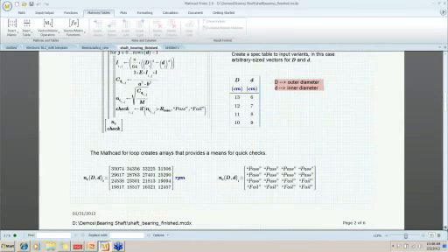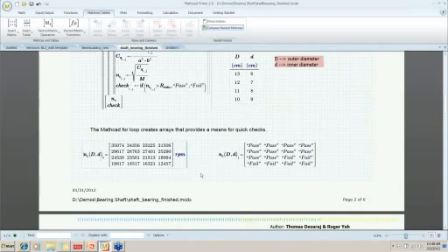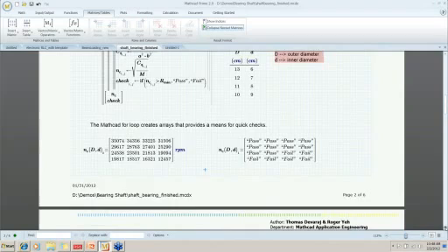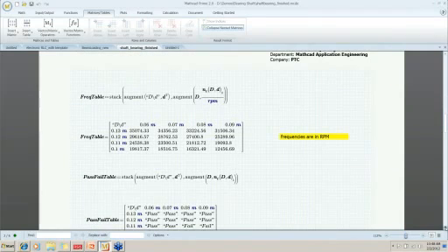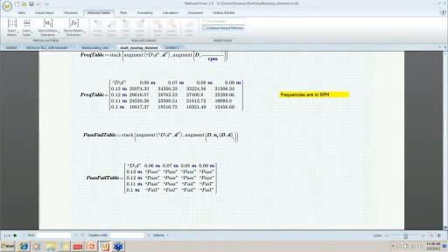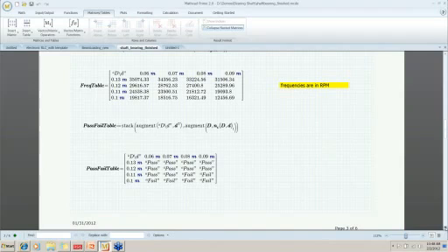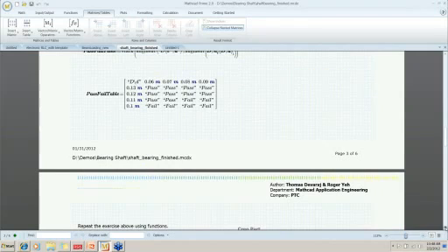And so here's our table of outputs. These are all of the critical shaft speeds we calculated, units of RPMs. Here's the pass-fail table. We have 16 entries. And all we're doing here is putting some column headers and row labels on so that we know exactly what numbers the calculations are using for outer and inner diameter. That's all that's doing. And then down here we have a couple of plots. So let me go down and show the plots.